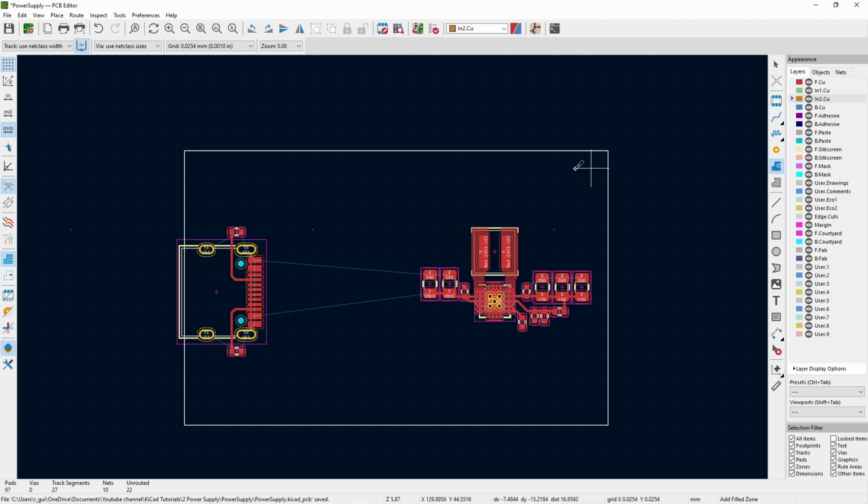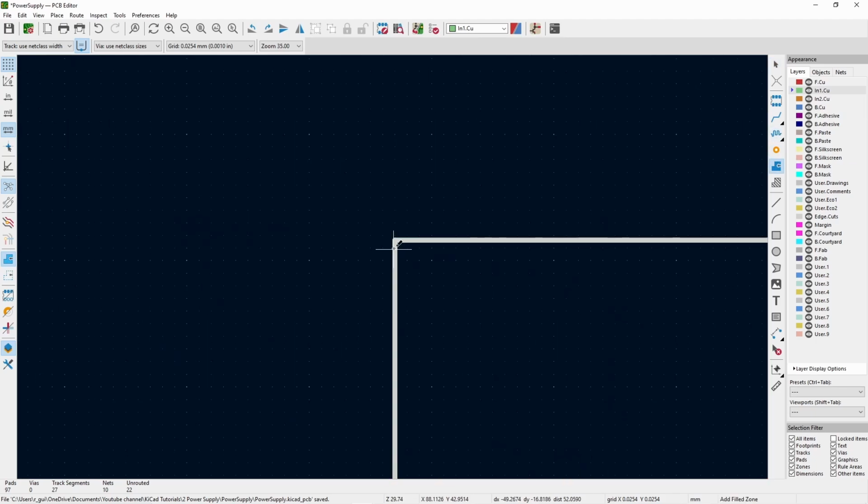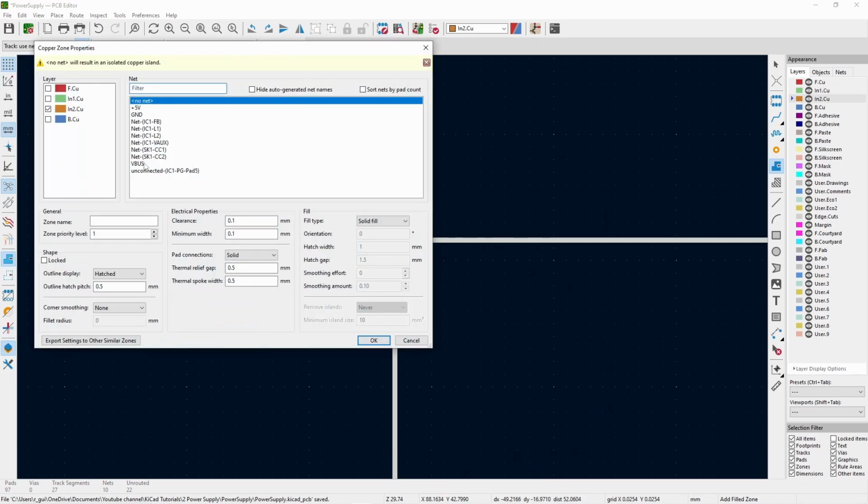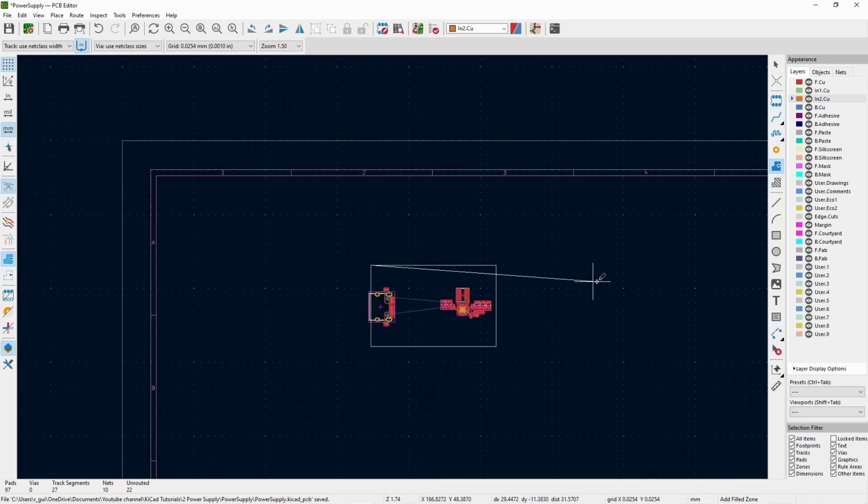What I'm going to do now is basically make inner layer 1 the power plane and inner layer 2 the ground plane. Obviously, if I realize at the end I don't need any of these, then I will just change back to a 2-layer board. But because I'm going for a slightly more complicated design, I think a 4-layer board will be ideal in this case.